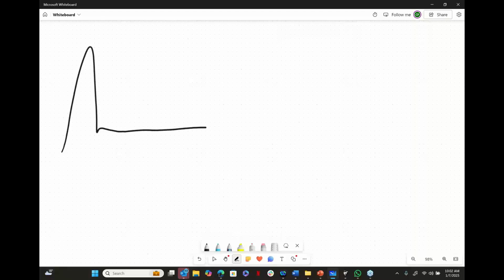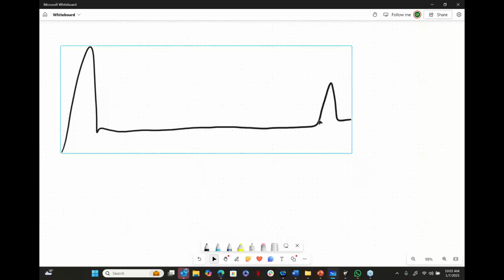When you first turn on your TDR and you have a pulse width like this, this represents the output pulse or the start of the signal, the B and C on the front or the back of your TDR, and then this would represent an open at the other end of your cable. It's disconnected, right? Everything in the middle right here, this line is flat. In a perfect world, a flat line means there's nothing wrong with your cable.